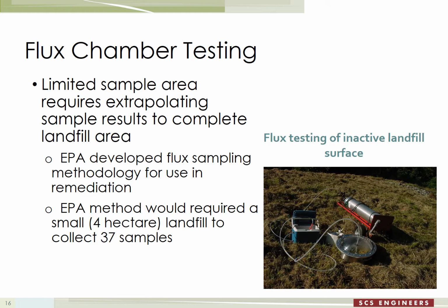EPA developed this methodology for use in site remediation, and it's been applied to landfills. If you follow EPA's model directly, even very small landfills could end up collecting numerous flux chamber samples. And of course, the more chambers, the more analyses, the more expensive it gets.